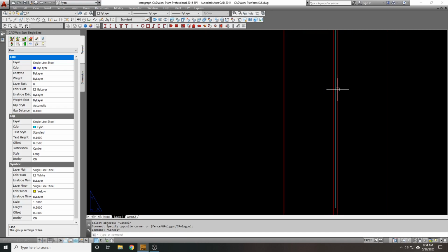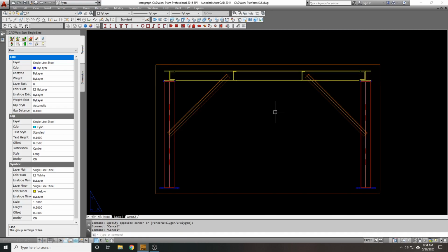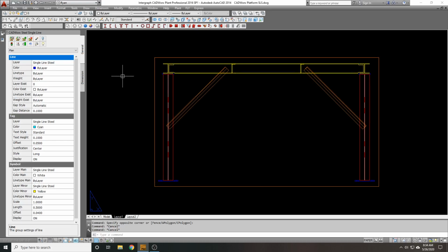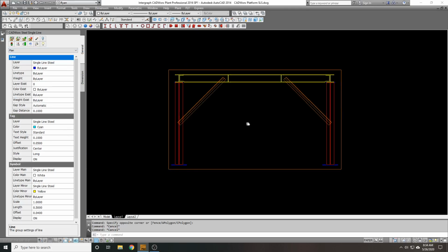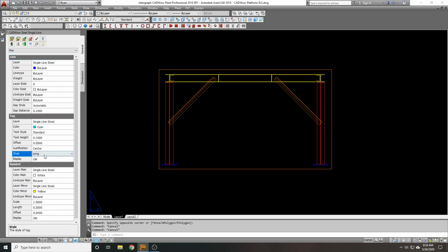It looks like I left a work line in there or something. Okay, so let's start making some settings. I don't have to tweak too much. The only real thing I want to tweak is that now that I've done long annotation in this view, I want to do short annotation in this view. So I'm going to choose short annotation, and I believe everything else will be the way I want it to be. So I'm going to save this. This is literally the only difference. Now you may have more things that you tweak.